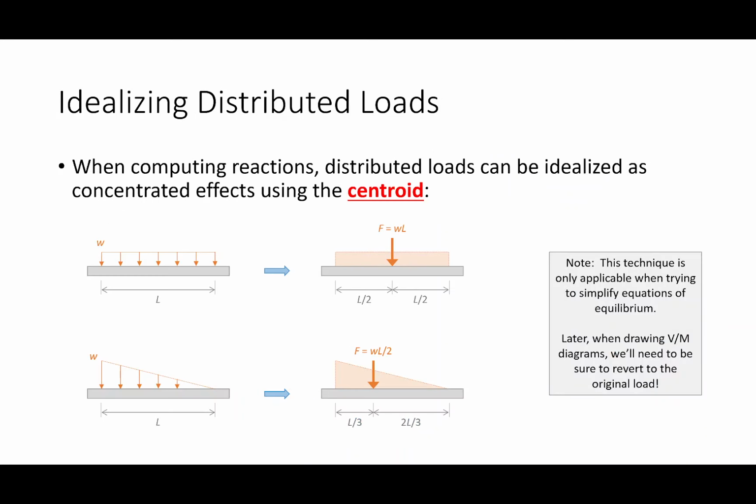Now, I seem to remember this Engineering 213 statics class that tells me that if I have a rectangle or a triangle, I can characterize those with both an area and this special point that we call a centroid. Y'all remember that? So, for example, if I have a distributed load that is W high and L long, I can characterize that by collapsing it into a single point load where the magnitude of that load is just the area of this rectangle. And the big question is, where do I put this load? I put it where the centroid is. Because if I collapse this into a single point load right here at the centroid, the magnitude of this load equals the magnitude of this load.